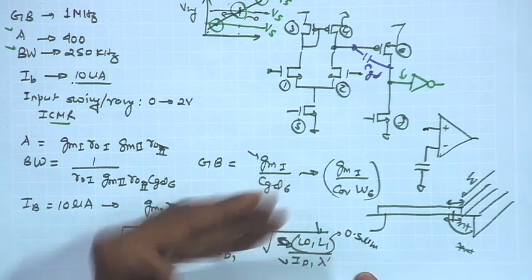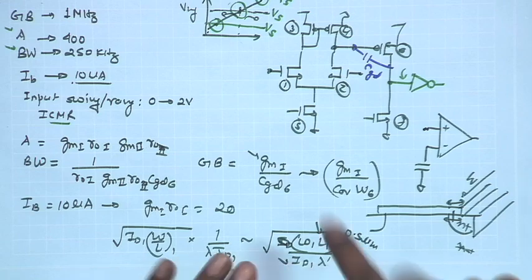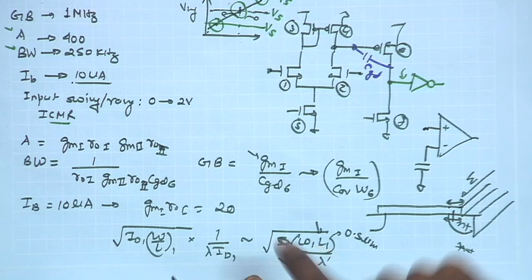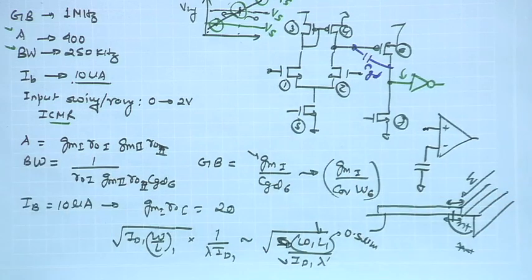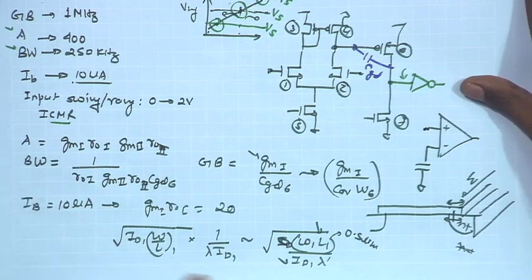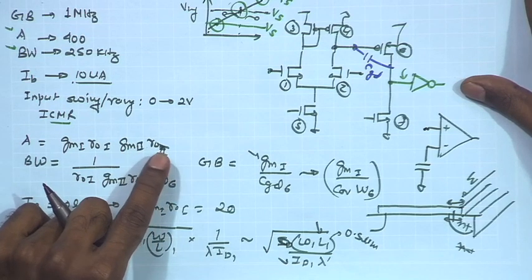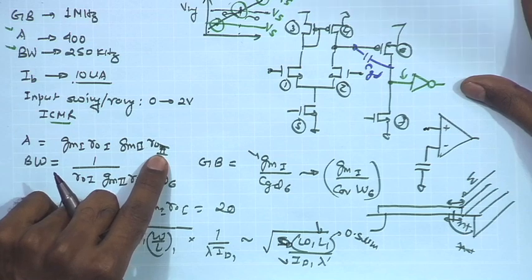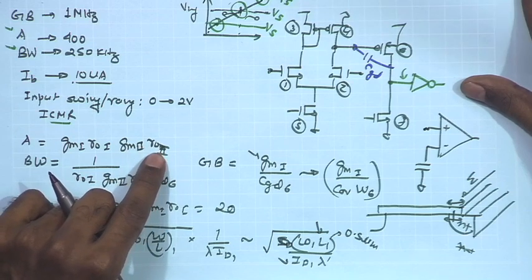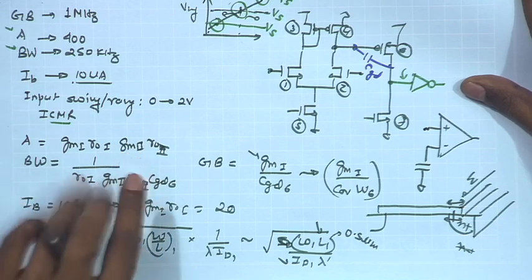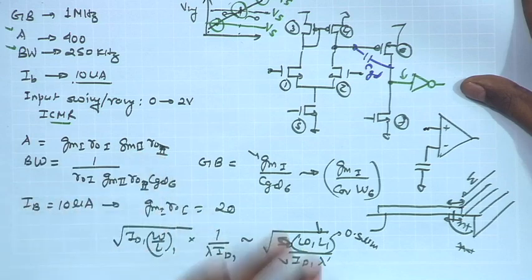For that, basically I need to determine what is the W1, so that you get a sufficient gain of 20 from the first stage. So, for this L1 I can determine the minimum value of W1, so that a gain of around 20 is achieved in the first stage. And likewise, if I use the same channel length in the output stage and almost similar bias current in the output stage, I have the corresponding value of RO2 coming into picture, and therefore, the GM requirement is also similar, and therefore, the W by L and RO are going to be related over here.